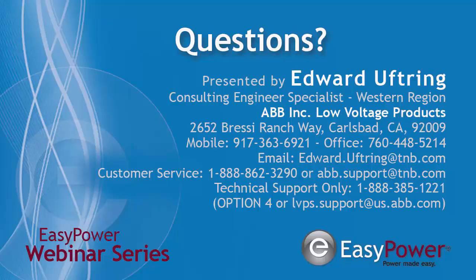What is the maintenance recommendation for breakers? That depends on your usage of the breaker. So if you're using it in an application where you're doing full load switching, you're going to have to maintain it often. The neat thing about our breakers is there's an indication. You can get it electronically because we do speak Modbus, Profibus, and 7 different protocols. So electronically, it can kick out and tell you the status of the contacts, the wear and tear, and when maintenance is required. And on our non-electronic trip units, we do have red lights that will indicate that the current is seeing a resistance that's not really expected, therefore maintenance is required. So the breaker itself will tell you when it needs to be done.